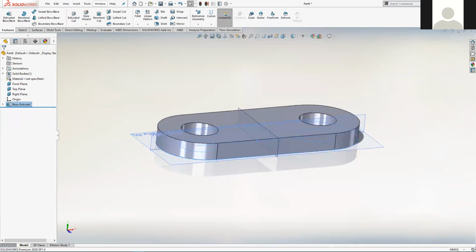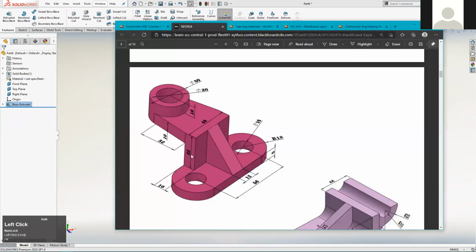So the next one that I did was that rectangular block there. I'd split this shape down into an initial plate, then a block of material that rises up, then this extra material here, which itself then has a circular boss, and then there's a cut that passes through everything that goes down through there. And then it's got this rib feature as well. But what I'm going to create right now is this box feature here that grows out of the top surface of our initial slot shape feature.